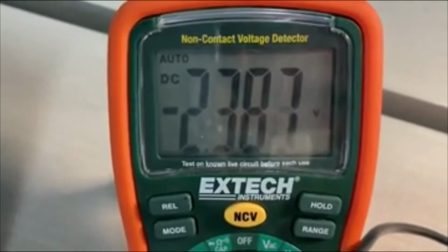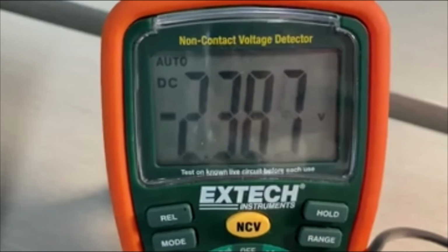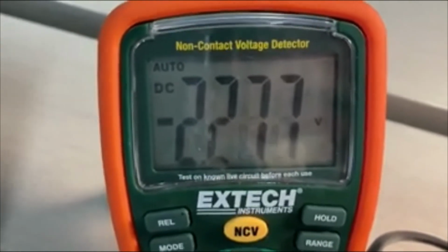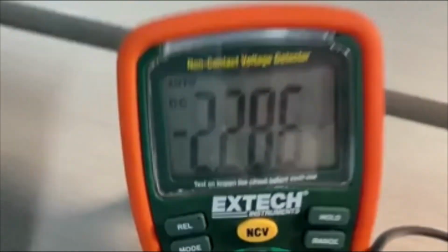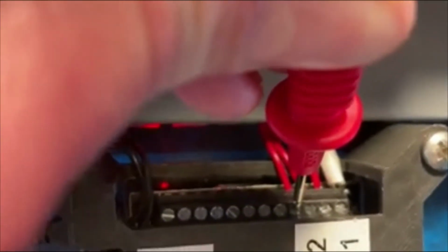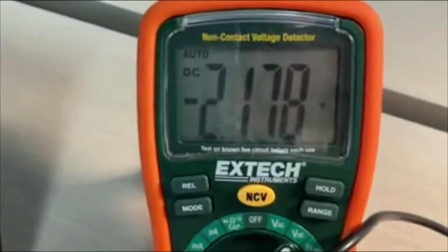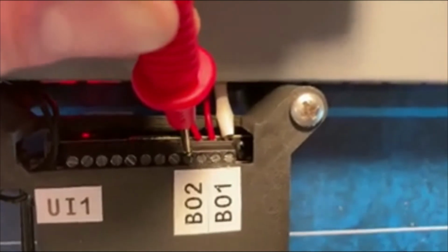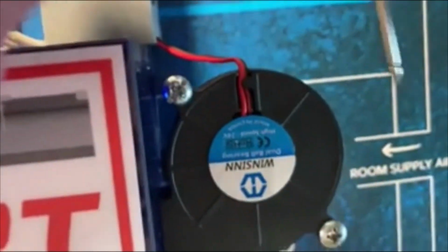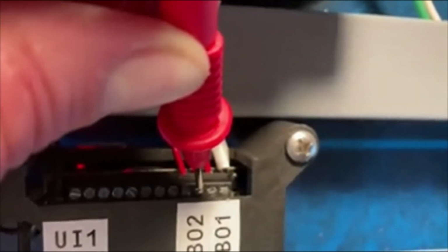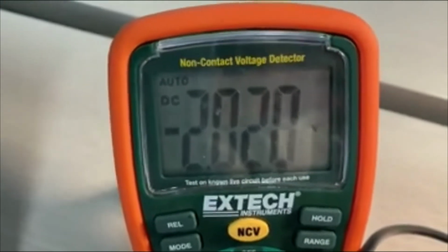And if we measure the other side of that relay, remember we're expecting it to be open, and it looks like it is. The relay is open, the circuit is open because we're receiving negative 2.3 or so volts through measuring that part of the circuit. So again, at terminal 4, power supplied at 27.68 volts or so. And then at terminal 3, we are measuring -2. So it looks to me like the voltage between those two is very different, not near 24 volts, which is the power that this fan uses. You can read there's 24 volts required to power the fan. So obviously when we're measuring -2 at terminal 3, that would mean that the fan is not receiving the full voltage that it needs to run.